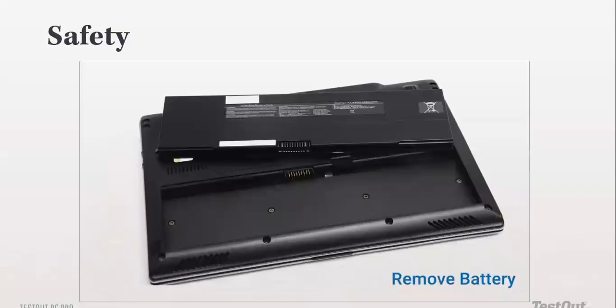And in cases where you can't disconnect the power from these devices, always make sure that the power connector that has 3 pins is plugged into a wall outlet that has 3 pins, so that the grounding pin is always there working. Your manufacturer will not give you a device that needs 3 pins for you to plug it into an outlet with just 2. It means the third one, the grounding pin, which is actually very necessary, is not working.